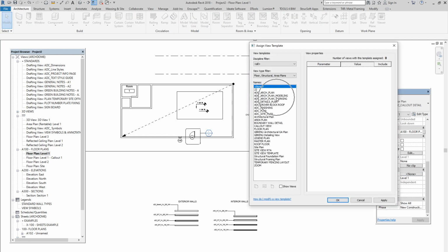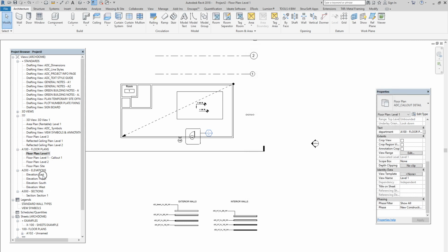We just have to select modeling or working, and this is already a visibility and graphics tool which can control the visibility and the graphics for the view, floor plan, section, elevation, and so on, and the way of presentation in printing, PDF, DWF, and so on. And we will explain later how to control all of these issues, also if you want to create some changes.